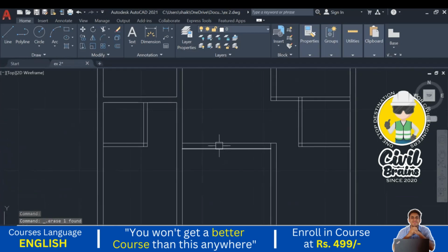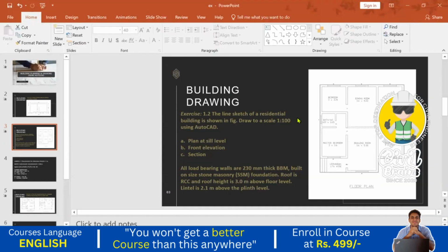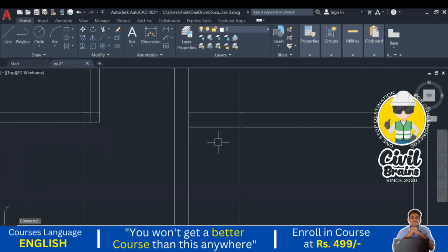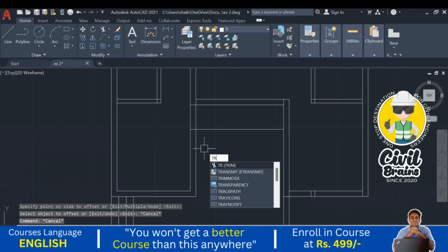Next will come here. These are dotted lines, I will tell you how to do that one. From here to the entry of this one, where it is, just check. Okay, this end of the dotted line, here it is the main door entrance. So I just go here, I just extend this one, EX, enter. Okay, from here the door size is given 1 meter, take an offset, I just provide it over here, and I trim.